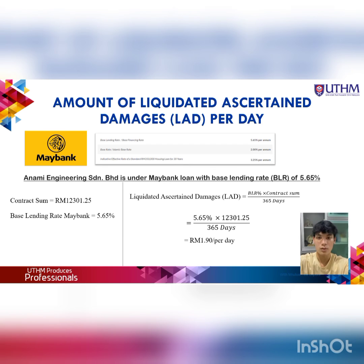Okay, now we move on to the amount of liquidated ascertained damage (LAD) per day. Our company is under a Maybank loan with a base lending rate (BLR) of 5.65%. So by using the LAD formula, the percentage of BLR, which is 5.65%, needs to be multiplied with our contract sum from the previous slide, which is 12,301 ringgit and 25 cent, and we got the value of 1 ringgit and 90 cent per day.